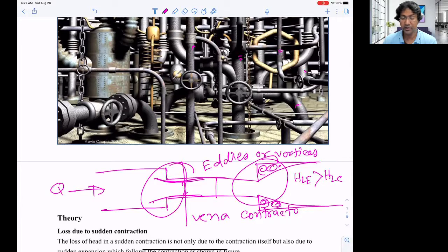If you know that, then you can consider while designing the distribution system that, okay, I need to focus on this part or that part, and I can even neglect those settings or fittings. I can only consider this one. So you have to be able to understand. You can neglect all of these minor losses, but you can't neglect or omit the major losses